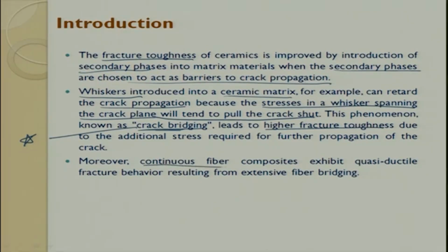When we are using a continuous fiber composite, it exhibits quasi-ductile fracture behavior resulting in extensive fiber bridging. But please understand, reinforcing a ceramic fiber into the matrix is really a challenge while manufacturing. It is very easy to manufacture particulate type or whisker type ceramic matrix composites.